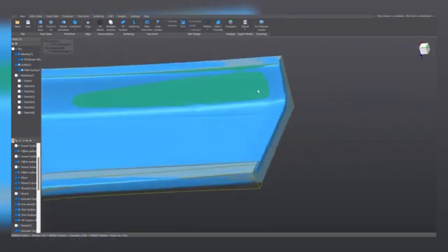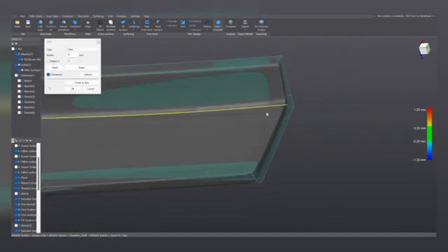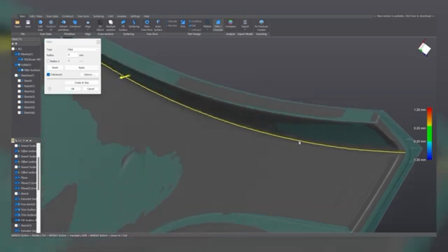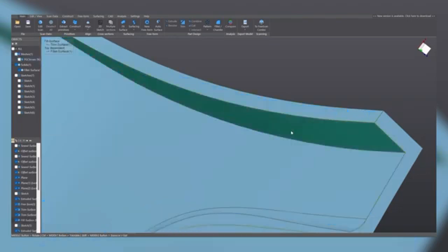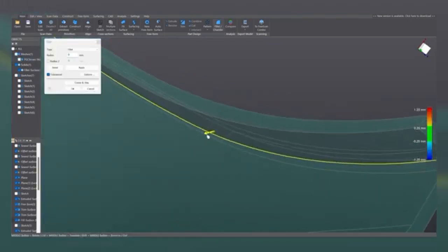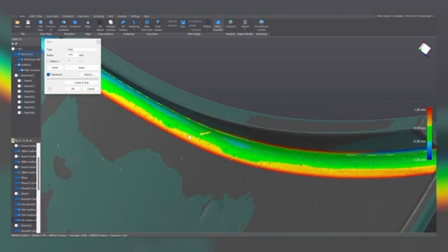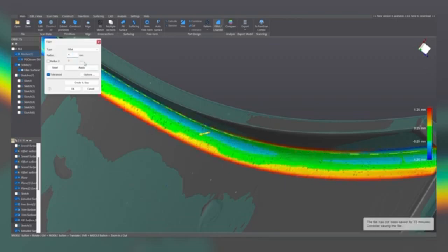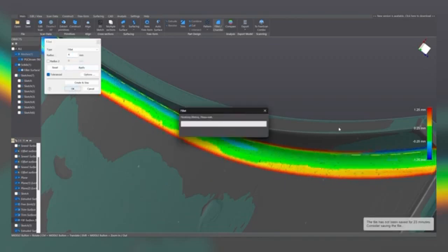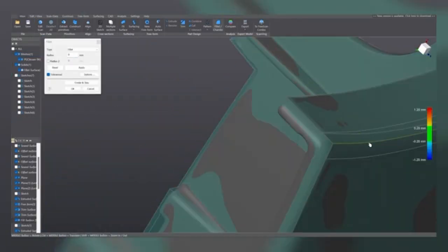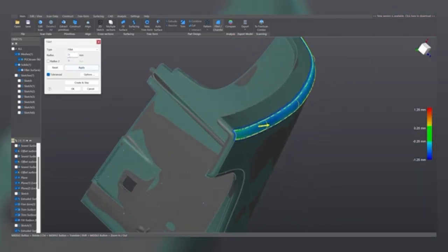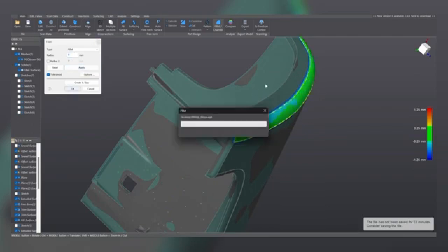And let's do the same on this side. Let's drag this arrow. Hold on. Let's choose it. Let's select it again. Display the mesh. Let's drag the arrow. Yeah, let's try with 4. Apply. And actually, let's use the same value here on this side. 4, apply. Maybe a little bit more. Let's use the 6mm. Okay.